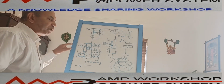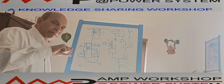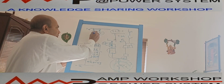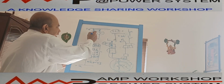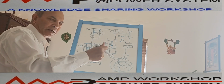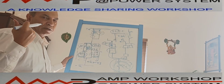Okay, so in this scenario, how is this circuit preventing closing and tripping if you maintain the closing command? Now consider this way: the moment I close the breaker, immediately I open it. I leave the push button, then the push button will come back to normal. It is a spring return push button. If I consider this a spring return push button, the moment you give the command, immediately it will get closed. You leave the push button and it will come back to normal.